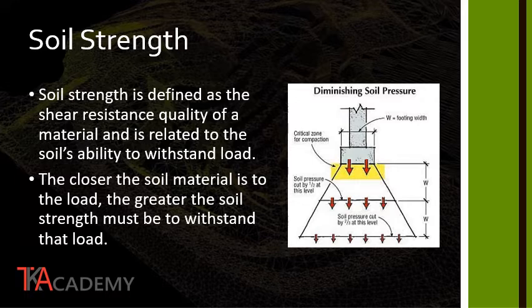All the soils that are located in this trapezoidal area directly underneath the footing are key in resisting the loads that are being transferred from the building into the ground. This is why, when excavating next to an existing building, it is important not to disturb any of the soils that are within this area, as measured from a 45-degree angle from the edge of the footing.